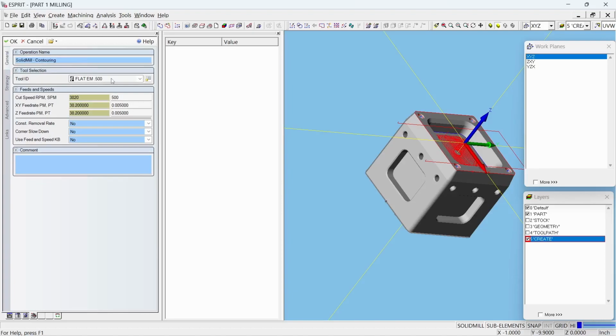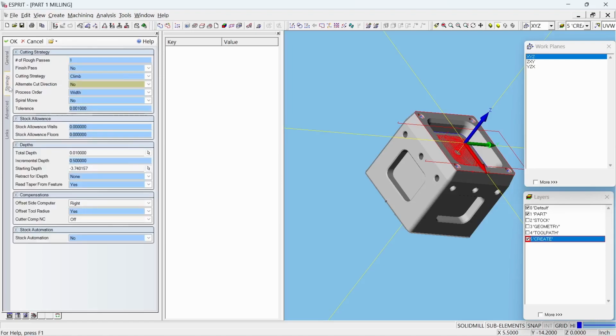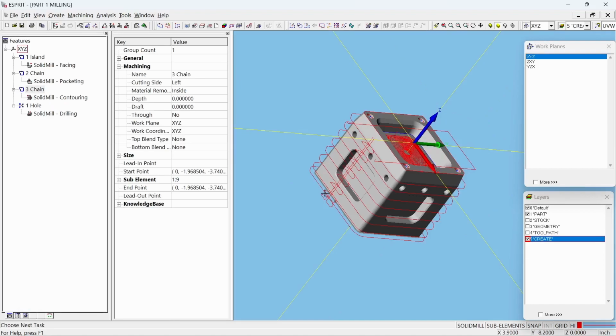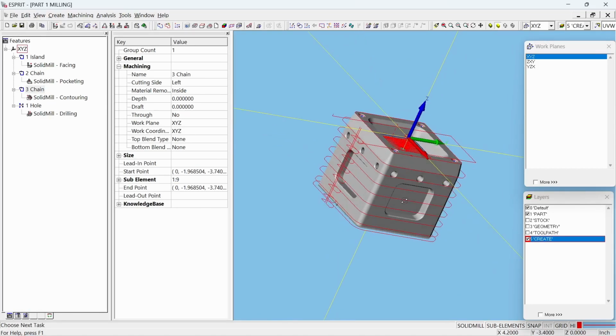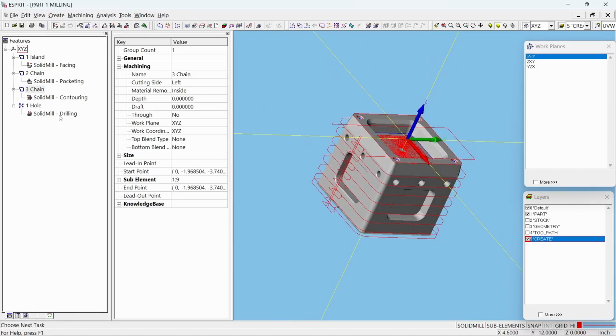Contour, flat end mill. It's the long one because it's almost 4 inches. So everything out here, what's important? Okay, just finish. If you want rough, then you put something here. You want a little bit deeper, all right? That's where they start, and this is the step down. And right, so it cuts from outside. If you choose left, the tool paths will be inside. I tried already, so that's why you can see it fairly easy.